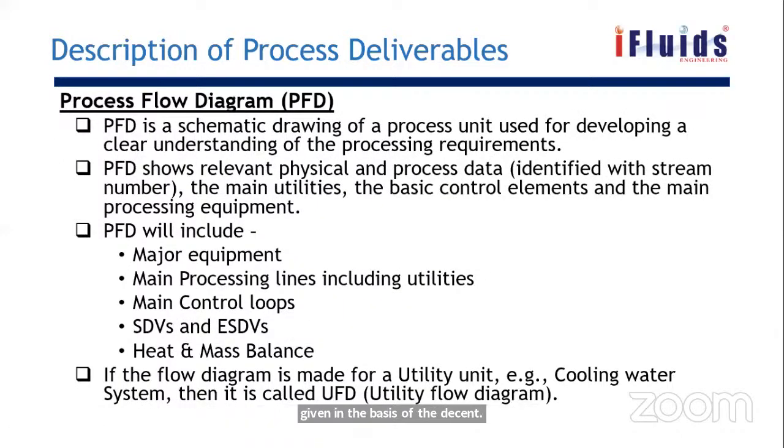And then the PFD; we also have a part of this in this session. The PFD is basically extracted from the simulation study. The PFD will cover the basic equipment, major equipment, the major process connecting lines, and the major controls will also be considered in the PFD. From the simulation we will be extracting all those things, and then we put the controls in the PFD.